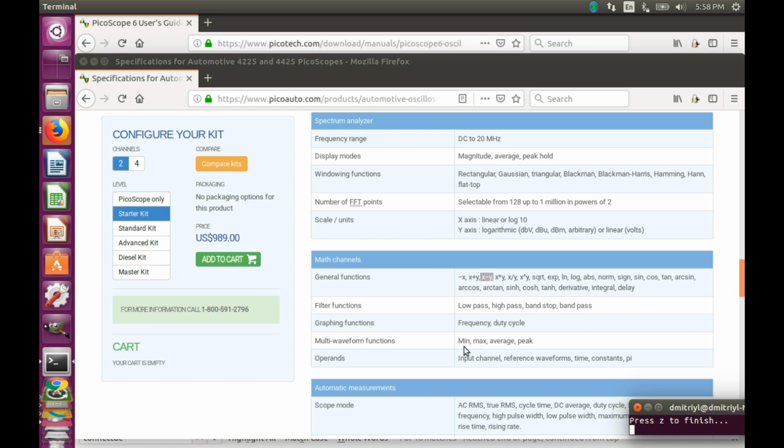Even though the voltage difference is going to be small, maybe under 1 volt, the resolution of the output is going to be dictated by the resolution of the original input channels. So there is no magic over here. You have to be aware of the resolution and the precision of the output, which is directly related to the precision of your input.